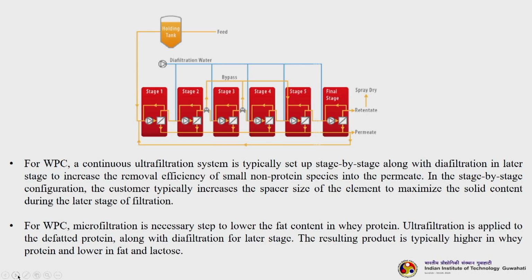For WPC, microfiltration is also a necessary step to lower the fat content. Initially, you use the microfiltration membrane to remove the fat content. Ultrafiltration is then applied to the defatted protein, along with diafiltration in the later stage. The resulting product is typically higher in whey protein and lower in fat and lactose.